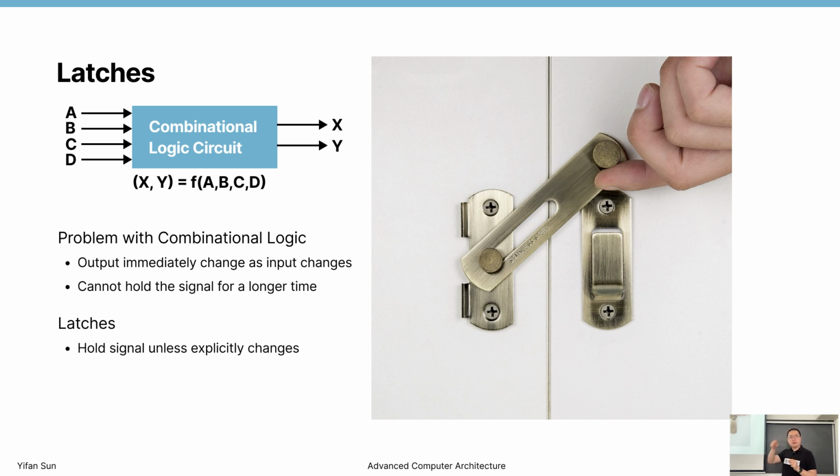So it will prevent those noisy times, when the signal is jumping around. Then eventually we wait a little bit until it arrives at a stable output. Then our latch comes in: okay, let's update to the new state. Then the latch holds the state, keeps the output unchanged until the next round when we generate some other result. Then we latch there for another cycle. So that is the purpose of a latch.